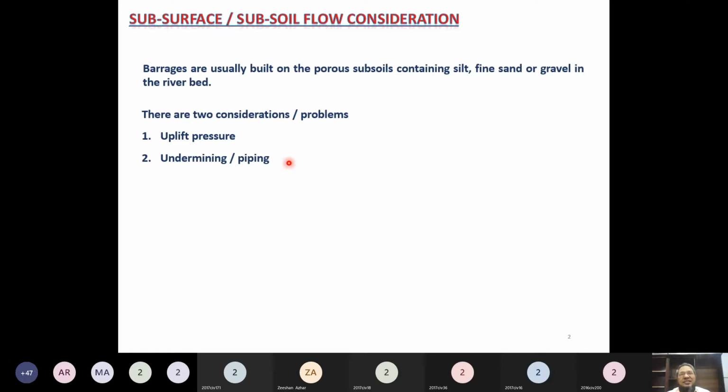So it means the resisting force to undermining is basically the submerged weight and the friction, whereas the disturbing force, which the water wants to push the fine soil particle out with, is the seepage force.